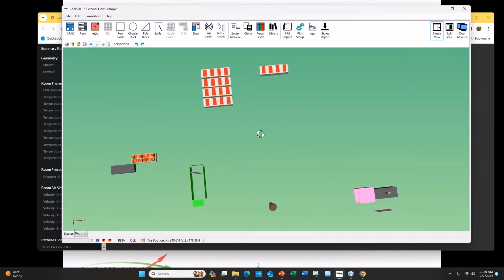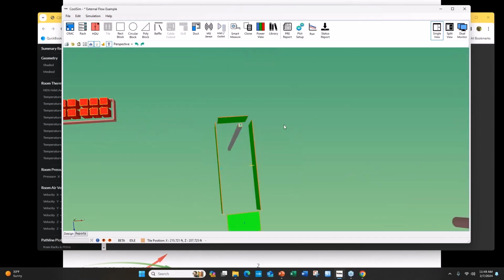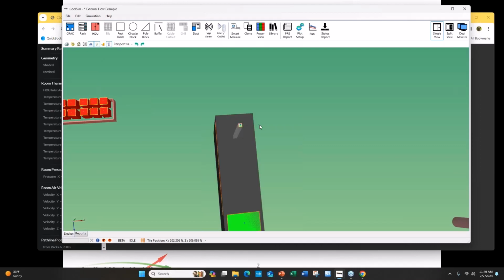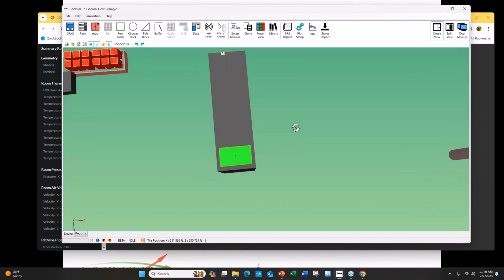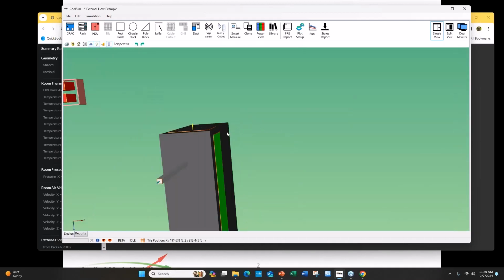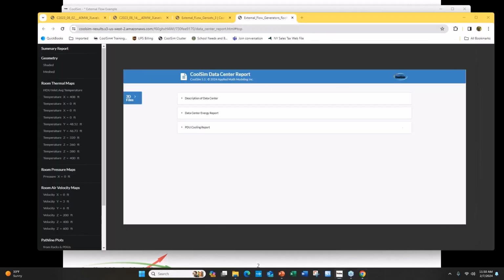It's not imperative, they still work, but it just meshes a little bit better if you get them lined up perfectly. In a case where you've got them on either edge, you do need to leave a gap. For example, in this case, we had to leave a gap between those edges because you've got an outlet there and an inlet here. If they touch, then it sometimes causes the solver to get a little confused about which is which. So in this case we've had to leave the gap right here on that leading edge in order to keep them separate from one another. So just a couple of tricks about how to build good structures.